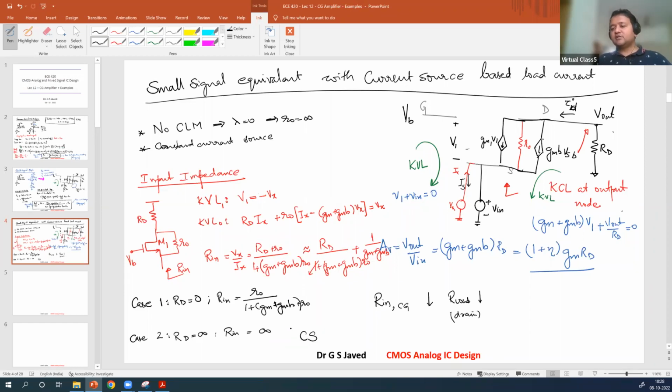So this is the common thing with this. In a common source amplifier, Rin is always infinity because the input is applied to the gate. In this case, if your load is low, then your Rin also is low. So that is one understanding that you have to do.